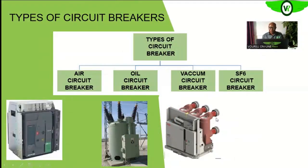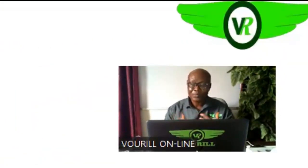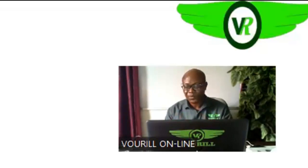But there is a stage to which you can reduce the vacuum, and when the vacuum is subjected to high voltage, as the voltage is increasing, there is a tendency for the formation of X-rays, which will have its own safety concern. So for those very high voltage environments, vacuum circuit breakers have their own limitations. They cannot be used in very high voltage and extra high voltage environments because of the formation of X-rays.